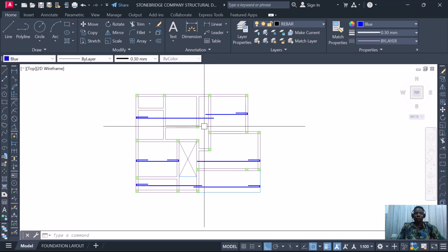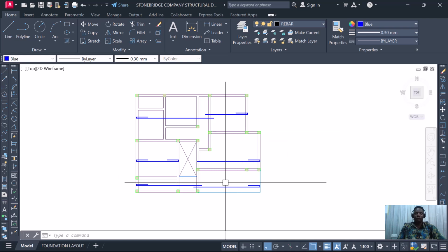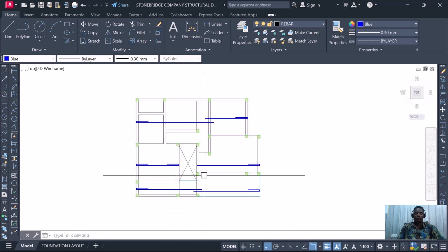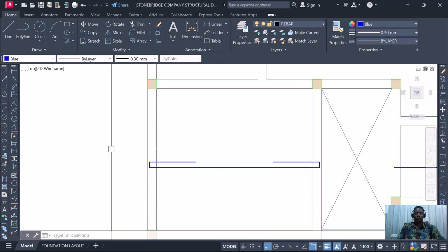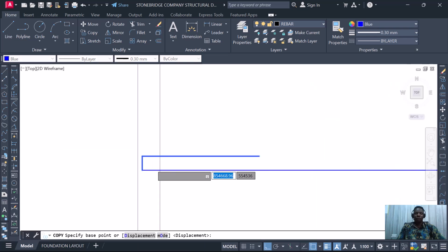So you can see in this area now, I create my lapping along this beam, and over here, because of this shorter span, I want this panel to run from this beam here down to this other beam. That's why I need to position it along this one. I want to support it here, not naturally supporting it here. Or I can extend this to support it over here. Take note of all those things. To support the lapping, the positioning is very, very important.